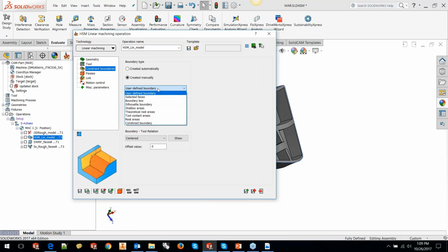Okay, but remember, you cannot edit a roughing toolpath, HSR toolpath, using a 3D boundary. It will not take into account. It will just project it onto a plane. It will make it a 2D boundary and then edit it. Okay, the result will not be what you would like. You can use 3D boundaries only for finishing toolpaths.